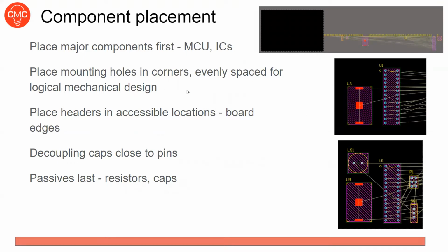Generally, if you have something, so the badge we're designing, the clock tower is not something that's being mounted anymore. It's not actually like a functional thing. It's just basically a toy. But if you have an actual PCB, usually you're going to have mounting holes in the four corners, so that it can be mounted to some chassis or like a stand for your testing. So generally, for your final product, for instance, you're going to want to place mounting holes in the four corners.